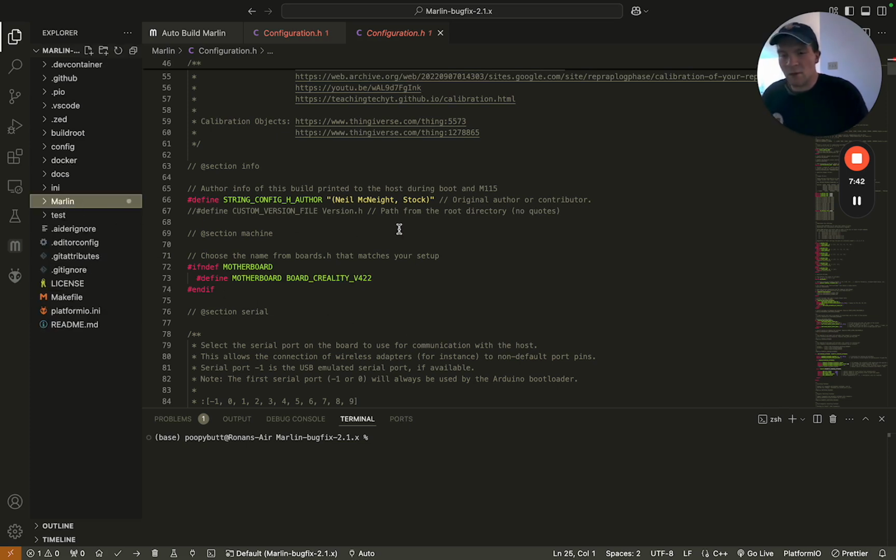I probably will go over my firmware build in another video. I started using unified bed leveling, which is great. It's really just set it and forget it. I did it once 2 weeks ago, and everything's been cherry since. Before, I was doing bilinear, like a 3x3 grid before every print, and that is so lame and so dumb. I mean, it worked, but it's so stupid. If you do bed leveling before every print, it takes so long, dude. Why would you do that to yourself? But yeah, in another video, I'll go over that.